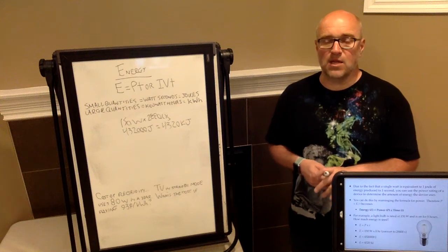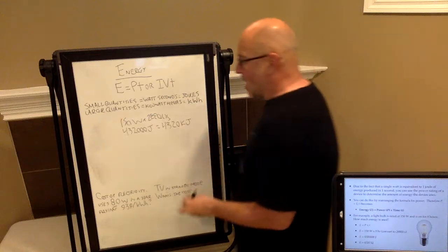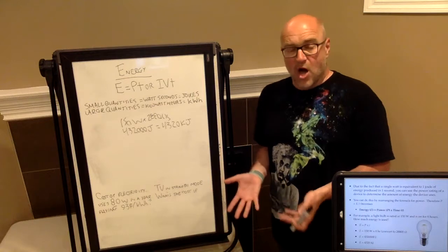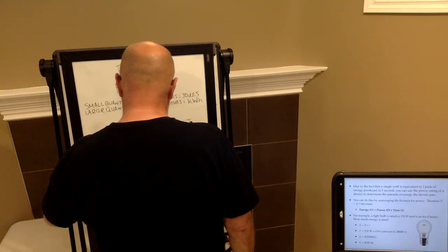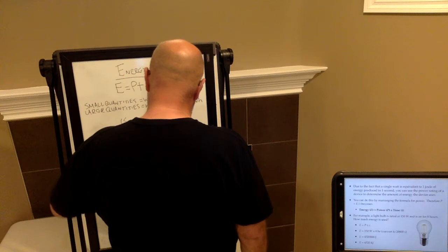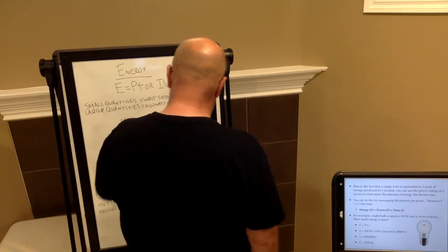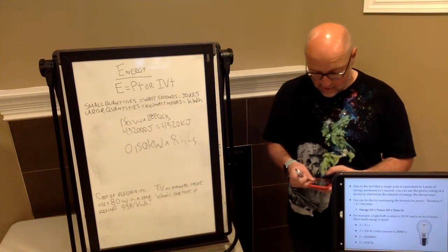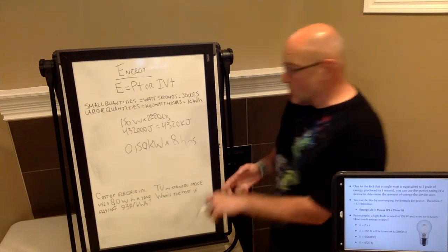However, some of you might have done it in kilowatt hours based on what I just discussed with you on the board here. That's actually the easier one to convert because I've already got my time in hours. All I got to do is convert 150 watts to kilowatts. So if I was converting it to kilowatt hours, it would be 0.15 kilowatts times 8 hours. Because it's not on the slide, I'm going to have to calculate this right in front of you. 0.15 times 8 is going to give me 1.2 kilowatt hours.